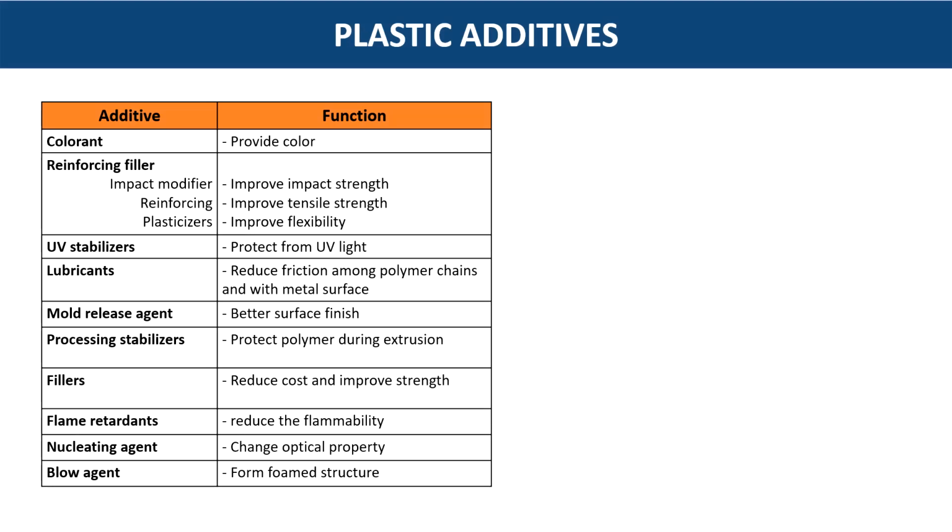Several additives, as listed here, are used to enhance the performance, appearance, and reduce the cost of plastic products. During product manufacturing, it is always desired to achieve the best performance at lowest possible additive loading, because a higher amount of additive will add to product cost and also may lead to deterioration of other properties. So, it is always important to use an optimum amount of additive.